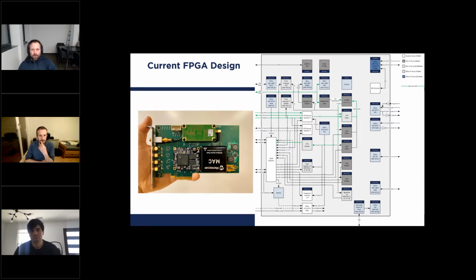So as long as the software is not completely involved in that interaction, which is why we are doing the extended design, you can have it running standalone and just fetch the time whenever you need, or fetch the timestampers. Of course, that is possible. You can also go command line to this interface. Currently a serial terminal would be enough. The GUI just sends ASCII text there. So it would be easy from any application via UART to get information from the design.